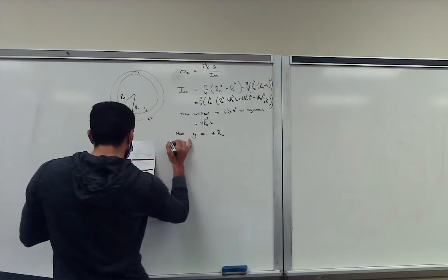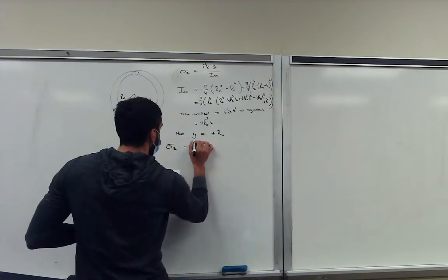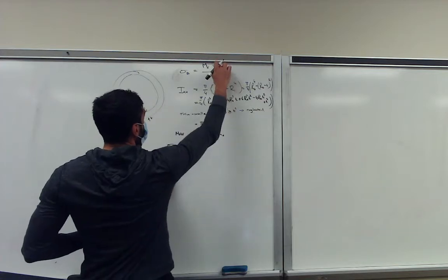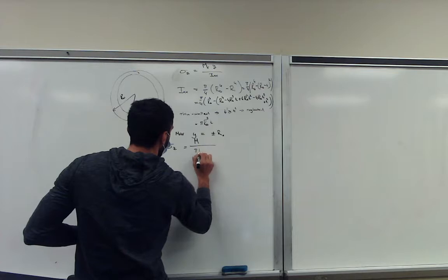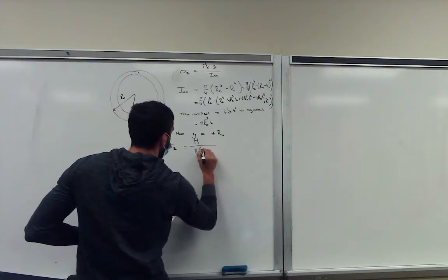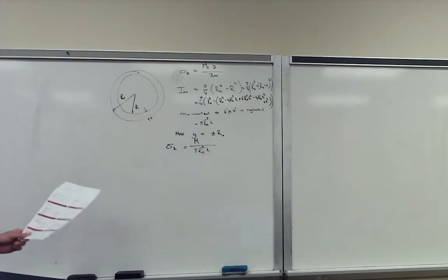So if we plug it in, we get for sigma z equal to the moment. We plug in r_o, it drops out with an r, so we get pi times the outer radius squared times t. So that will be our equation for maximum stresses.